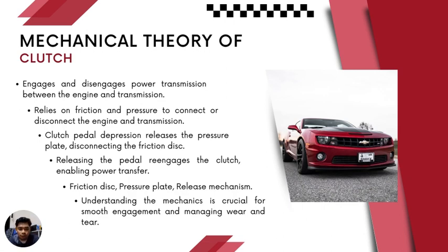So I will continue with mechanical theory of clutch. A clutch is a mechanical device that engages and disengages the transmission of power between the engine and the transmission system in a vehicle. It operates based on the principle of friction and pressure. When the clutch pedal is depressed, the plate releases the friction disc, disconnecting the engine from the transmission. Conversely, releasing the pedal re-engages the clutch, allowing power transfer.